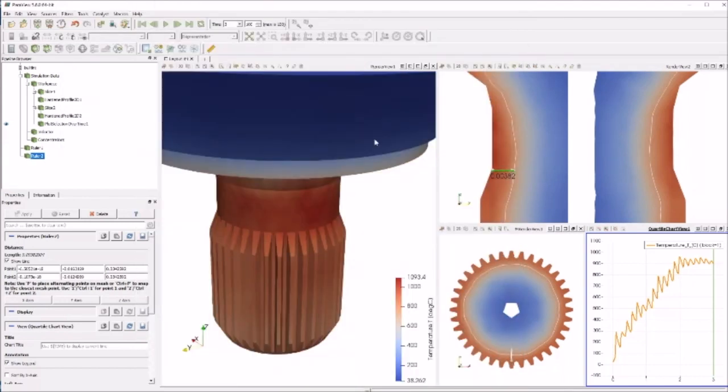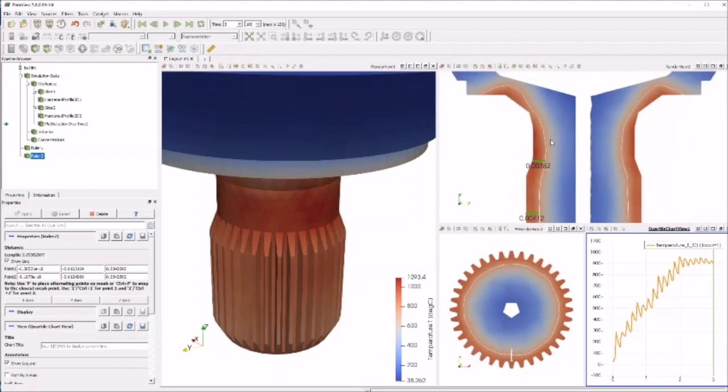So our customers just look at these results and make the next step, the next design decision. If your case depth here is not enough in some point, like for example here, you know that you can make some hypothesis of what you can change. For example, you can change frequency, or you can change power, you can change design of the coil, or design of flux concentrator, and go back and run simulation again.